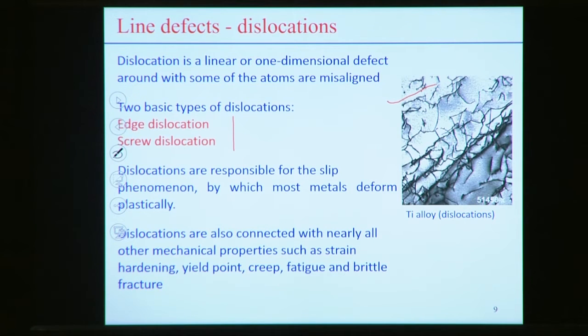Dislocation is basically simply a misalignment of an atom or a number of atoms, and that disturbs the regular arrangement of the atoms. Several dislocations can be generated, and a dislocation can move from one point to another point. This is one typical representation of the defects, specifically the dislocation, which is called a line defect. Basically, we represent the dislocation in terms of the unit of length.